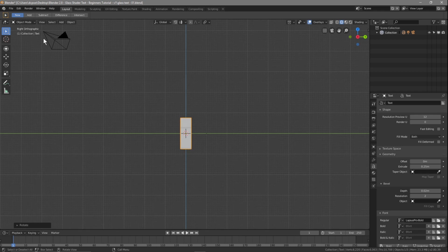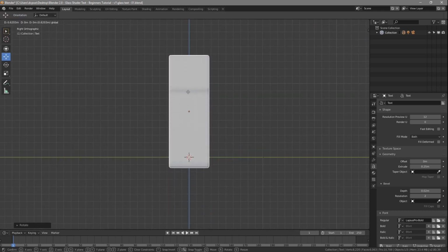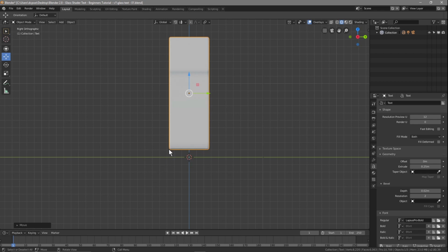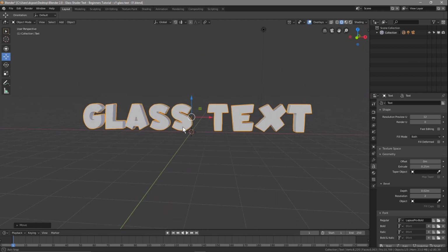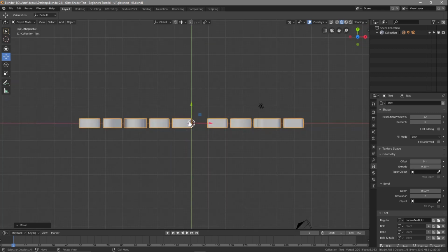Number 3 takes us to orthographic view, the right side. We'll click on the move tool, and we're going to zoom in and drag this text so that it is roughly one box above this green line. Then we can click and rotate. We've got our text here. We're going to press number 7. Number 7 takes us into the top view, and we want to duplicate this text.